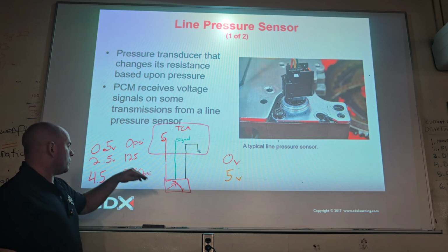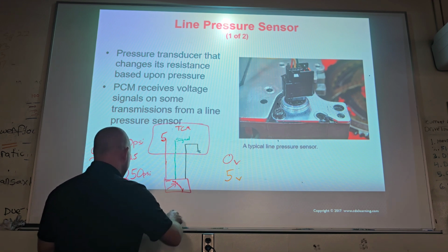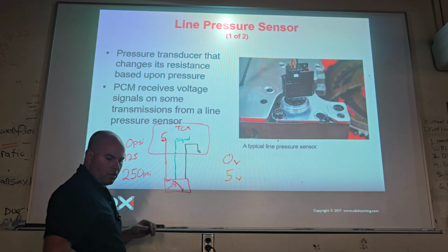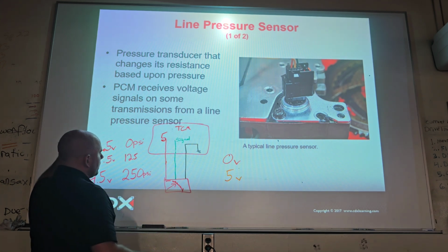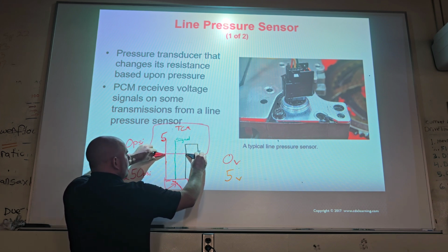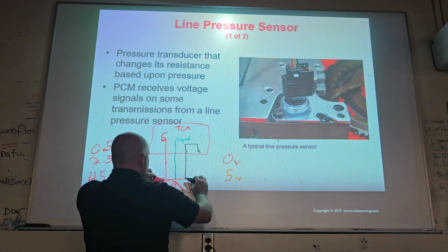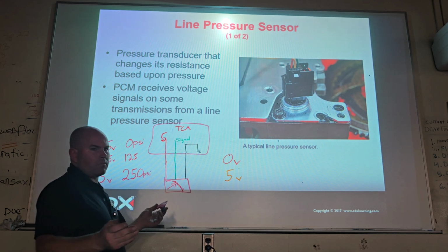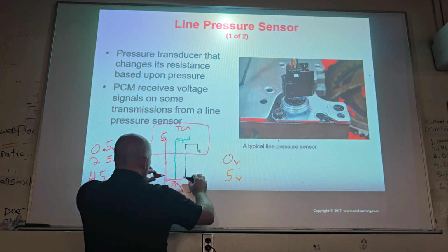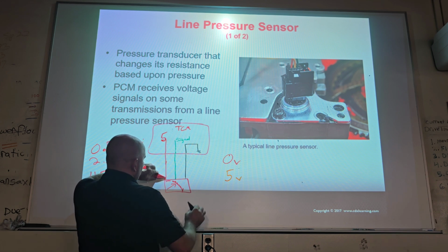So if you have 0 volts and you should have a minimum of 0.5, the way that we're going to go about this diagnosis is we're going to literally verify our 5 volts. So I'm going to take my meter right now. In fact, I'll use my meter clamp. Let me hook this to ground. Click. And let me hook this to this. What should my meter say? Should read 5 volts. Yeah, that's exactly right. And if it does, I actually could do it down here too. If it reads 5 volts and I have the ground on the actual ground of the sensor, then that means my 5 volts and my ground are good. Up here and down here, you might consider measuring both. It's more important to have this one here and probably this one here.